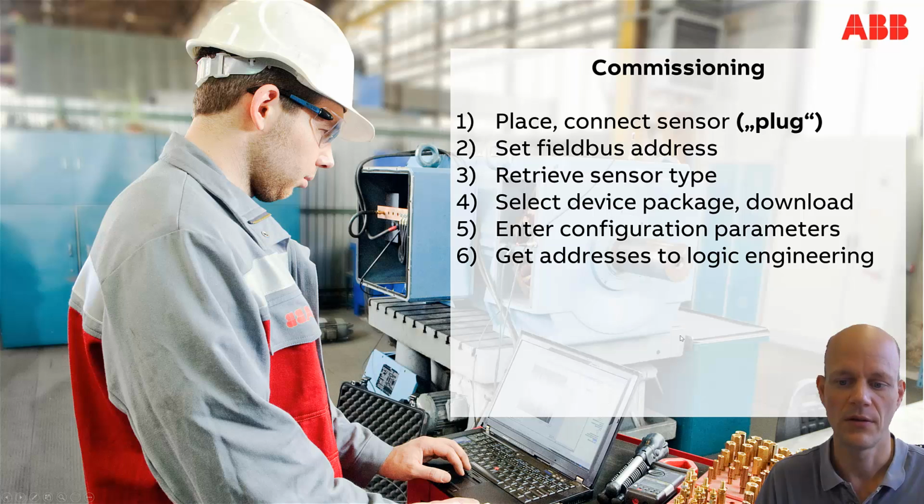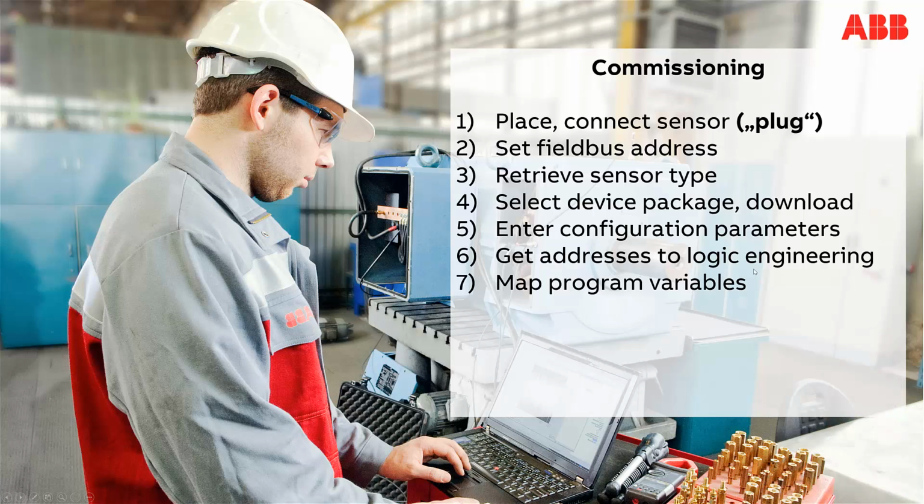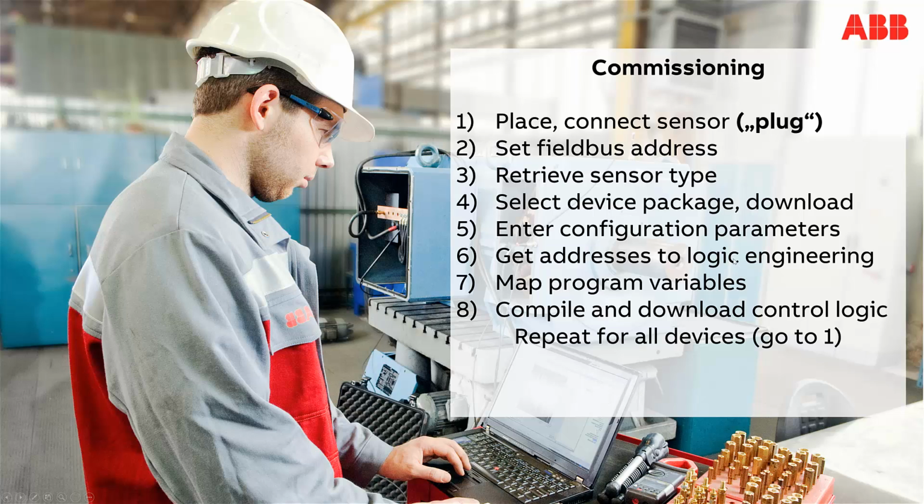You get the addresses and have to map them to the logic engineering, and then you map the program variables that you have in your logic engineering onto those field bus addresses. Finally, you can compile and download the control logic for that device, and then you have to repeat that for all the different devices. So this was only for one device, but if you have 1,000 devices, it's a lot of work.